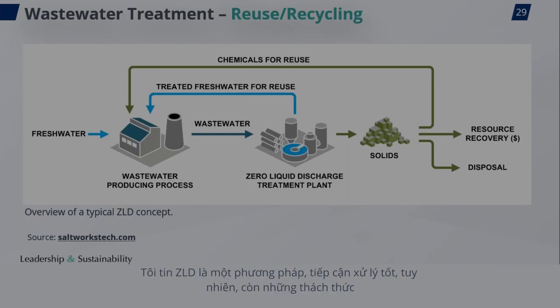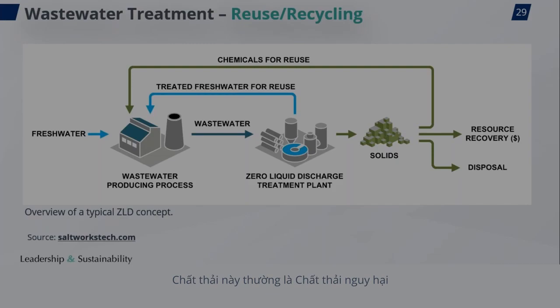What I wanted to say here as well is that I think the zero liquid discharge process is a really great treatment, but you also need to consider that at the end you have a highly concentrated brine or a salt, for example, and currently there are no good treatment methods for this. So it's basically also waste, and most of the time it is a hazardous waste that you have at the end of the process.